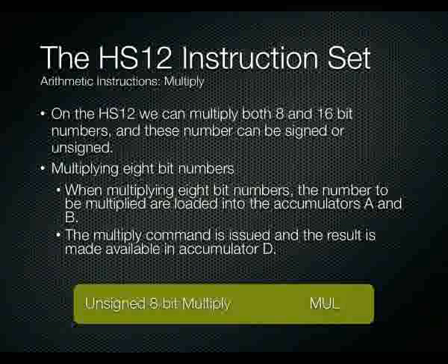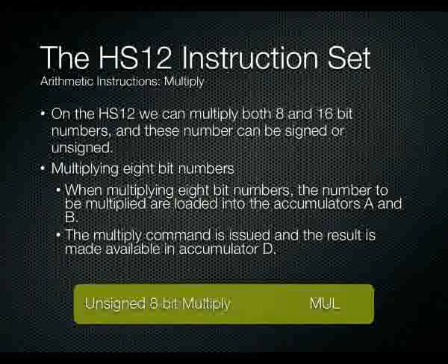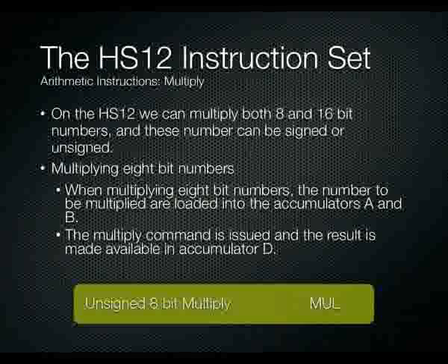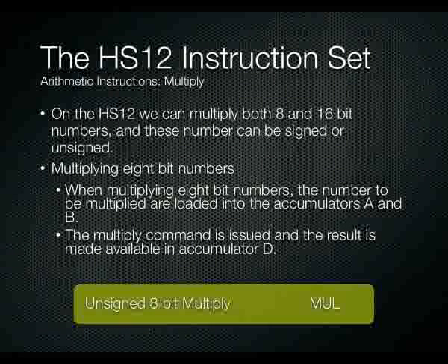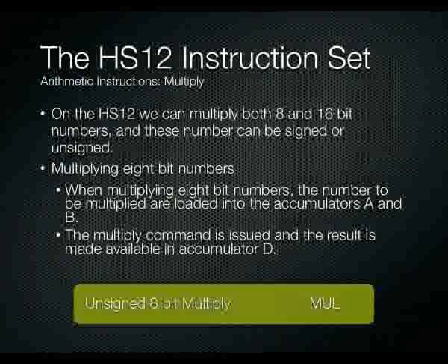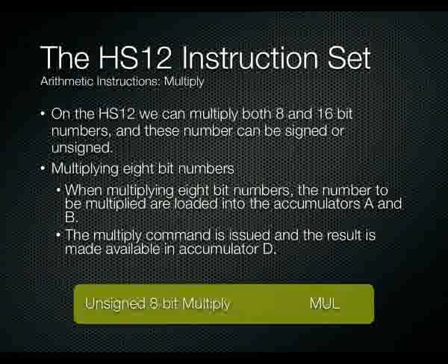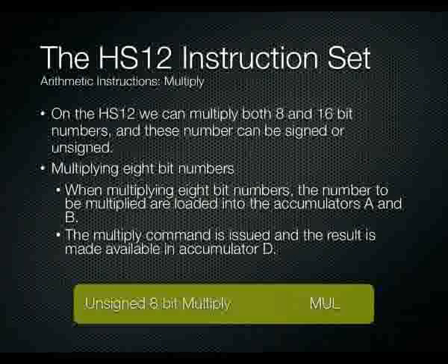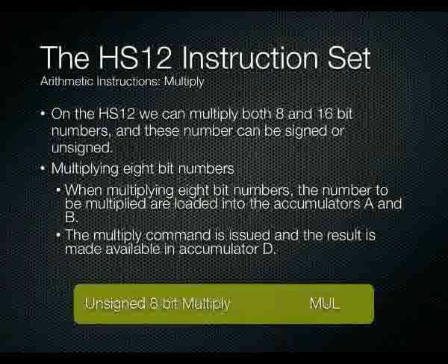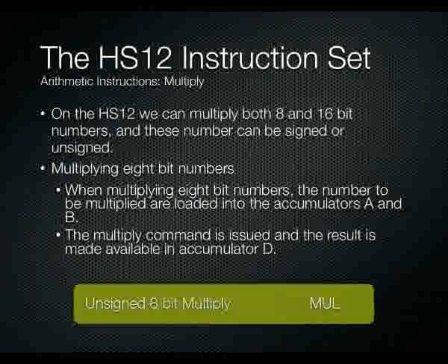One of the really useful commands on this processor, and probably one of the most unused, is the multiply command and the divide commands. Maybe because these instructions are fairly complex to use, but once you've got the hang of them, they're very easy and become second nature. When it comes to multiplying numbers, we can multiply 8-bit or 16-bit numbers, and these numbers can be signed or unsigned depending on what sort of instruction you use to do the operation.